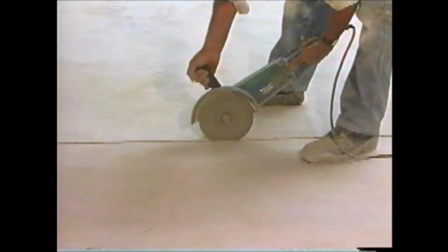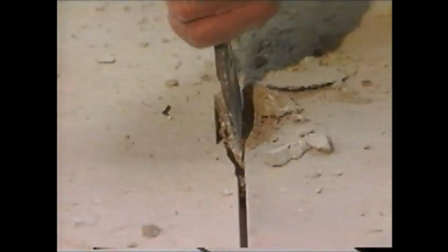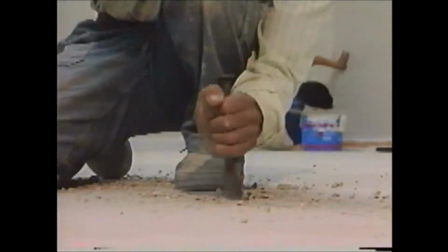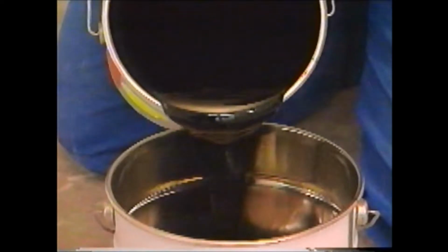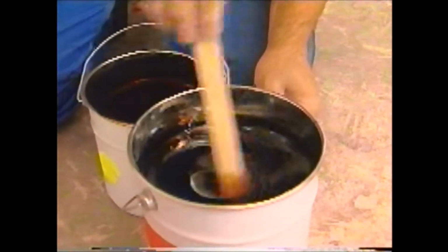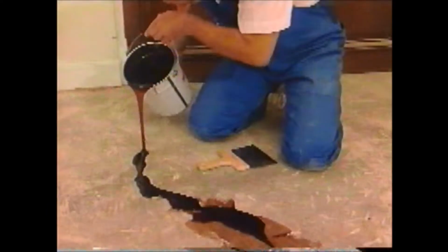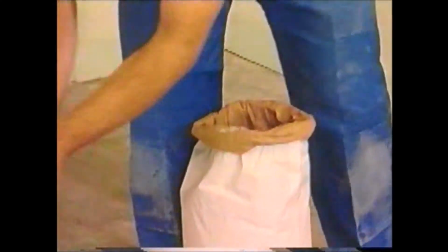Active cracks, or those that flare by more than 2/10, will be treated by opening with a power saw or chisel, sweeping and vacuuming, filling with epoxy resin, and powdering with sand to facilitate bonding of the finish.